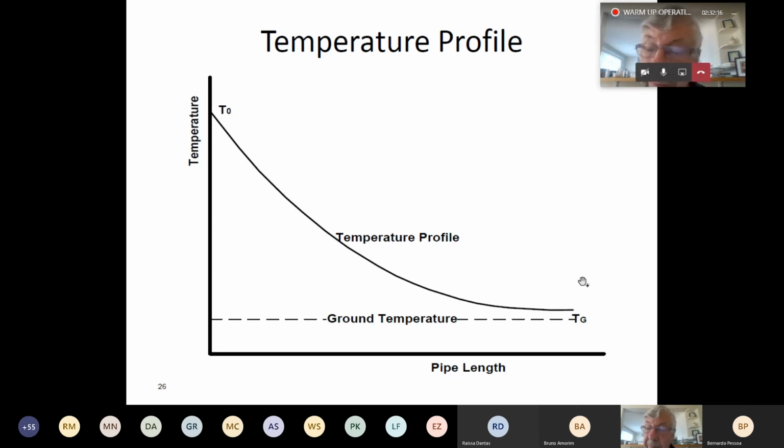And there's really two different types of compressor we use. Sometimes with gathering systems, we're dealing with relatively low flow, but we want to increase the pressure because the reservoir pressure might be low relative to the pressure we need in the pipeline. So you've got to use a reciprocating compressor. And reciprocating compressors are more forgiving of the quality of the gas coming in. If you've got liquids present, they can tolerate that.